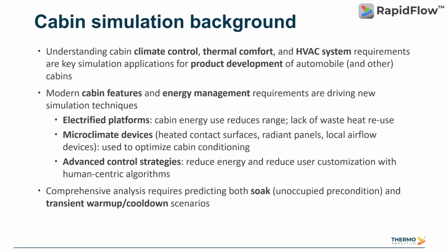And if we're going to do comprehensive cabin analysis, we really need to understand both soak modeling, the preconditioning that we see happening when the cabin is unoccupied and being affected by the ambient environment, and the transient warm up or cool down scenarios once the vehicle or cabin becomes occupied and we care about how quickly we can achieve comfort or the conditioning of the cabin.